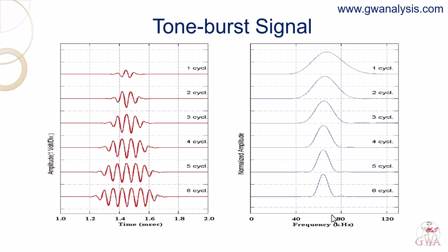To increase the spatial resolution, our transmitting signal needs to be narrow in space. Because the RF signal has time on the x-axis and the distance is a product of the time and the velocity, the signal width in space is proportional to the signal width in time. In guided wave testing, we recommend using 1 or 2 cycles to get a narrow signal width. A narrow signal width can differentiate two neighboring indications or differentiate a defect from a geometric feature.